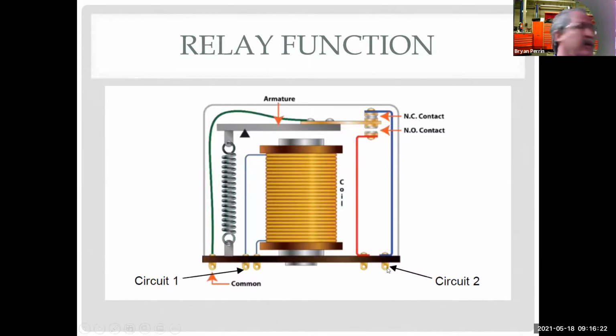There are times, just like when we did that blower motor drawing exercise, when the relay wasn't energized, the blower motor signal went through here, but as soon as we energized the relay for high, boom, this switched, and now we're feeding the power through here. So we're able to change the circuit. We have circuits that might be a default position on, and we only want a signal to turn it off. A lot of different wiring options with these.